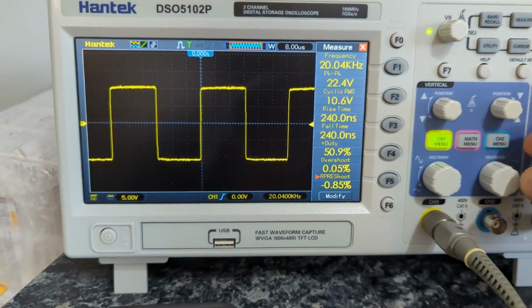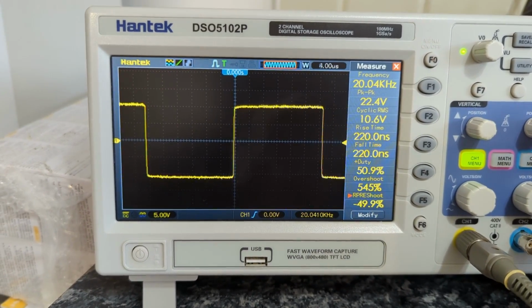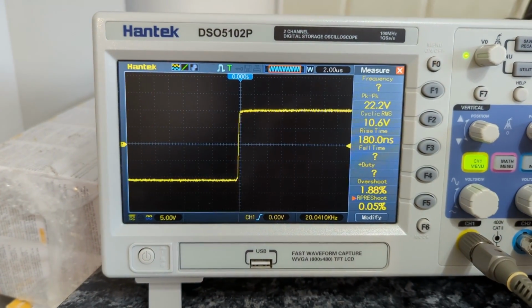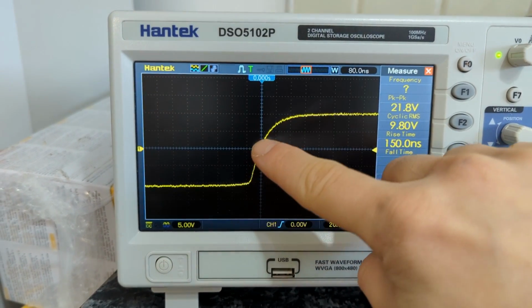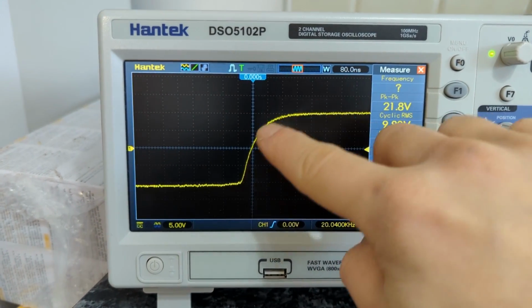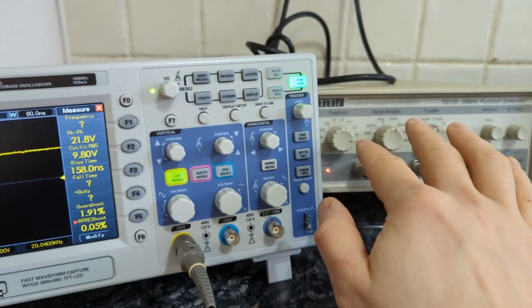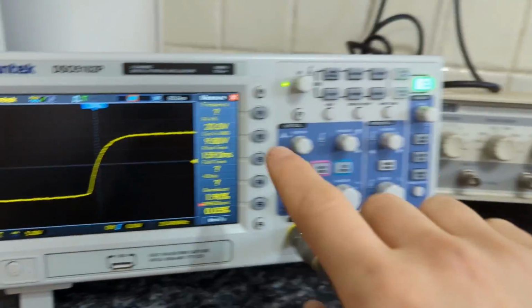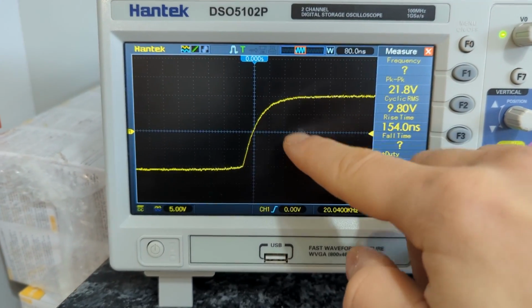So to measure the slew rate, we're going to zoom in quite a lot. So now you cannot see these edges, it's focusing on just this. And we're going to zoom in more, and you can see what starts to happen. It starts to soften the edge, and it's just a limitation of, I don't know if it's the scope or the generator, but probably a combination of both. And the amplifiers are going to have exactly the same thing, but it's going to start much earlier.